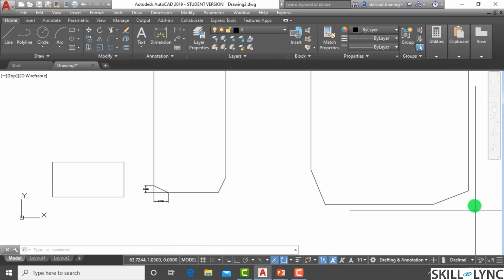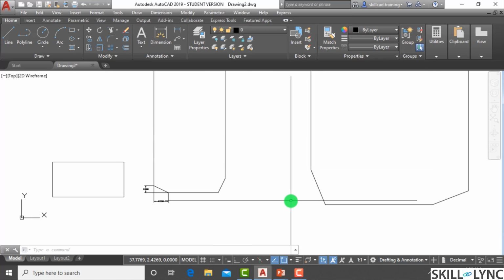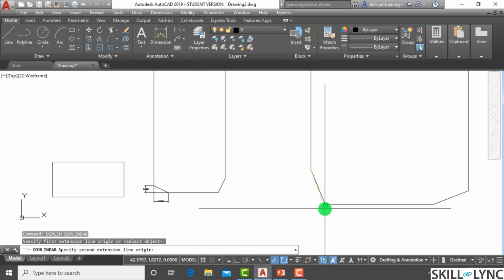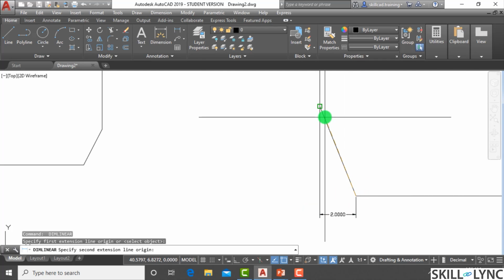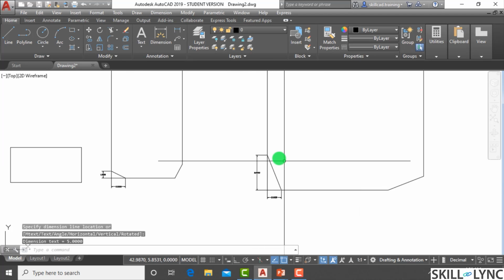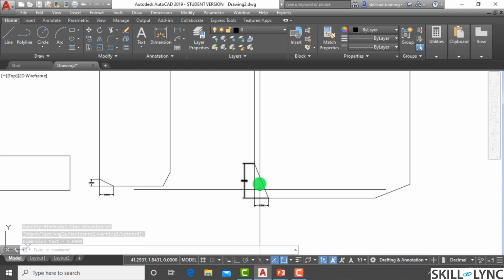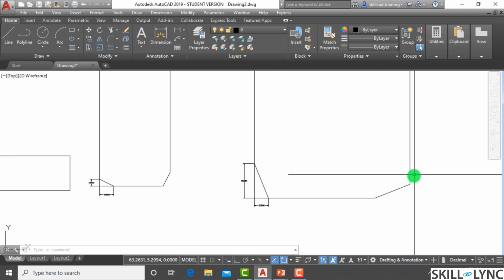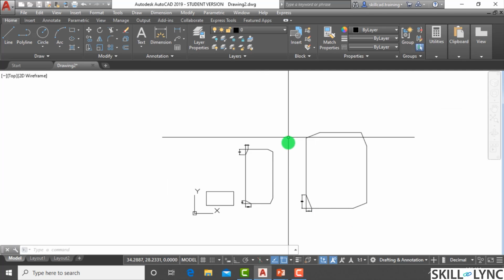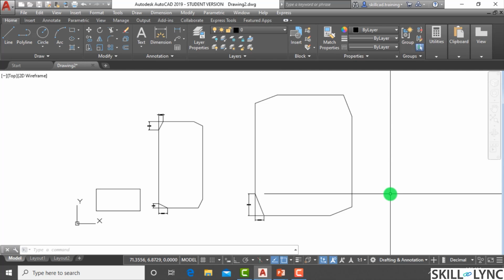First chamfer distance, second chamfer distance is 2. So you can basically imagine a rectangle with the corner point. The first chamfer distance is the y-axis, so this is, and second is this, and then it goes like this. So it creates a first chamfer here with 5 and 2 over here, and then 5 and then 2. So it goes in a counterclockwise direction here, like this.